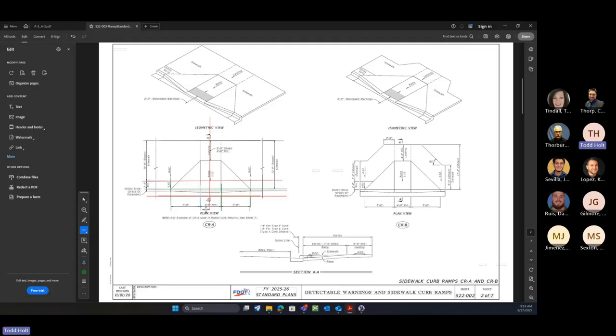So we have controls that would control our 4-foot minimum for the ramp. So we can grab those handles to make those adjustments, and from there we can go to 7 foot from either side. So when building the civil cell, think about the references, think about how you're going to make those modifications once it's in place within that civil cell. This is usually what I do when I'm building these for different agencies: I'll run through their standard plans and build that.